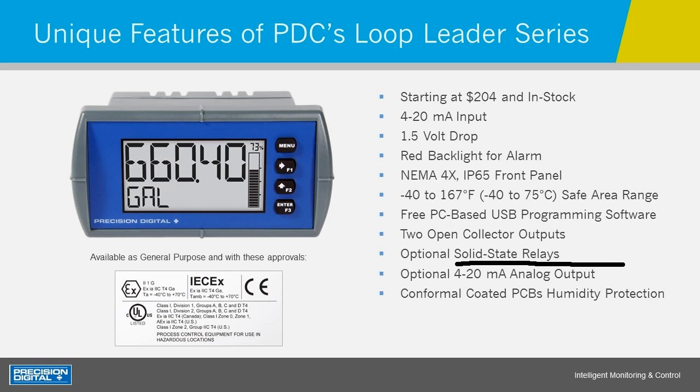So anything that you would do with a line-powered meter's electromechanical relays, well, you can do that with the Loop Leader's solid-state relays. They function exactly the same. They can push an amp of current through them, so they're pretty significant relays. They just happen to be solid-state.